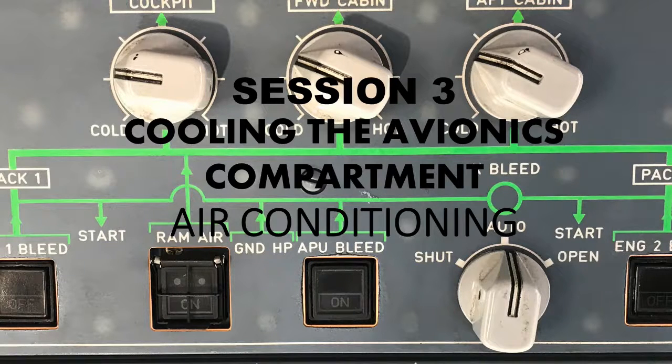Okay, so what's the threshold with these pressure switches? You've got a low flow indication. What is that defined as? Our low flow indication is going to be a differential pressure of 1.7 millibar plus 1.3 or minus 0.5 millibar. The pressure switches are installed in the cooling ducts, and they're going to be sending signals. When it's low, it's going to affect what shows on the display.